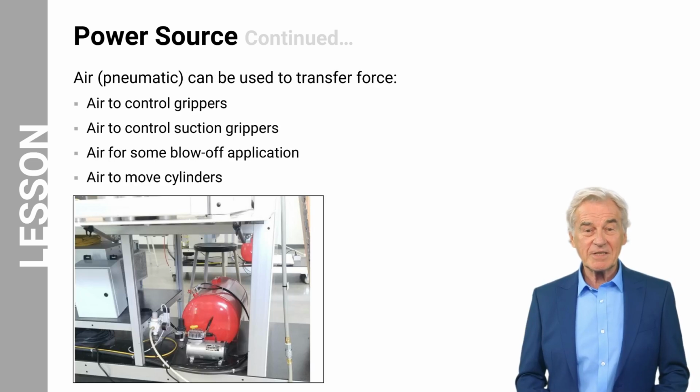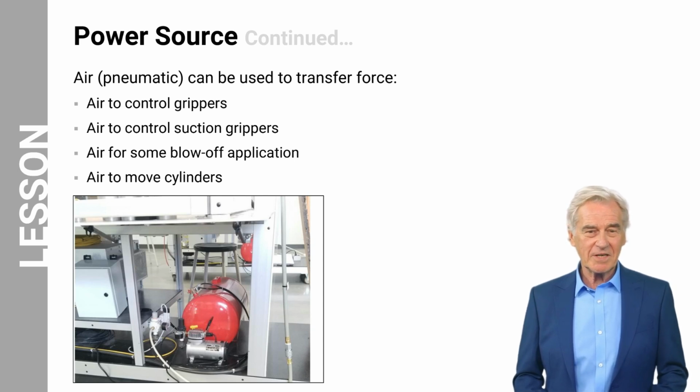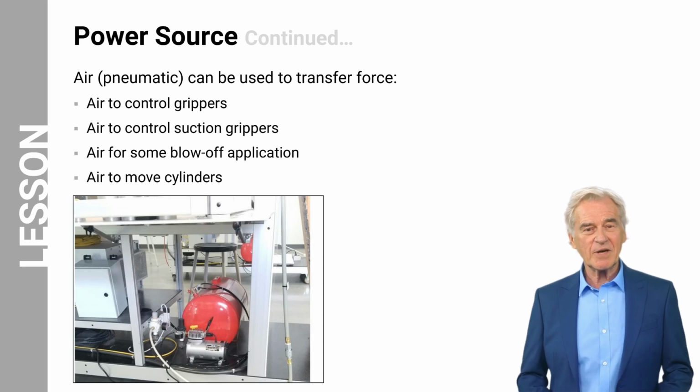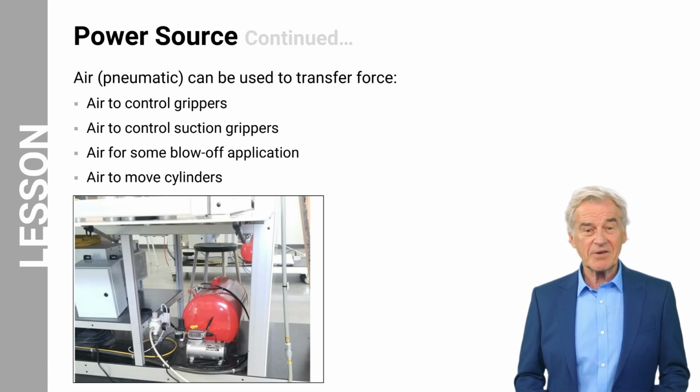Now, let's look at the pneumatic power supply, which utilizes pressurized air to transfer force. These systems can be used to operate control grippers, actuate suction cup grippers by applying vacuum or negative pressure, and perform blowing off applications for surface cleaning or applying finishes with pressurized materials. Additionally, pneumatic power can drive cylinders, like hydraulic cylinders.